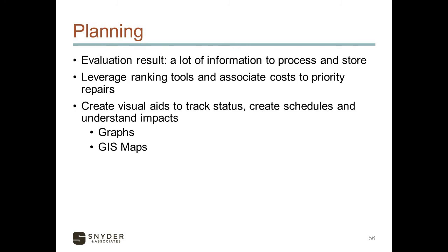Some of the planning that goes into this: through an assessment program, you're going to end up with a ton of information to store, terabytes and terabytes. Having a system in place to handle that and quickly reference it is going to be important. We're going to leverage the ranking tools we just talked about, take that risk assessment and associate costs to those priority high risk assets. We're going to create visual aids to track the status and create schedules to understand impact through graphs and GIS maps.